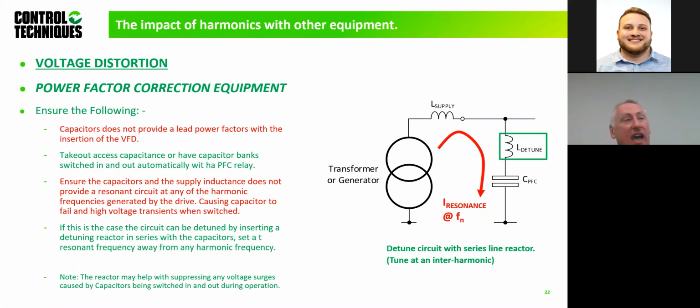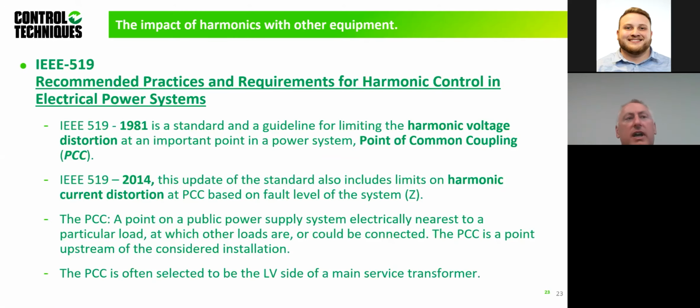Again, the reactor may help. An input line reactor to the drive could help as well with that sort of scenario. So just be aware of this PFC. It's an important point, especially on larger drive systems where you're going into a plant.